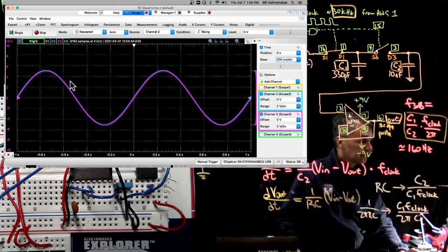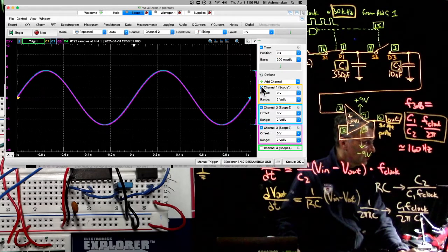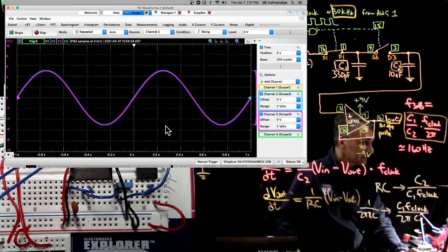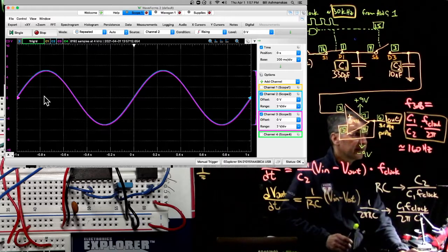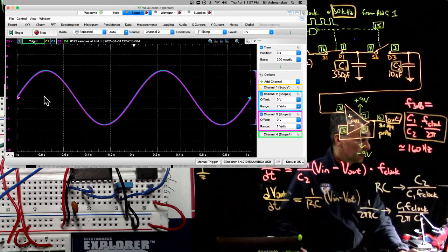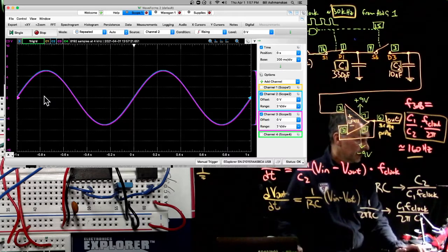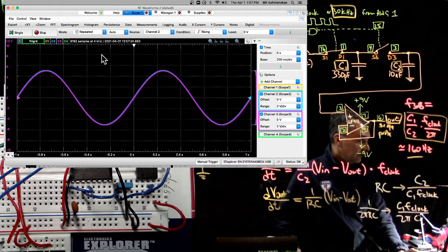Then let's look at the scope. Here's channel 1, which is looking at the 30 kilohertz clock. That's kind of hard to focus, so we'll look at that later. Channel 2 is the blue or cyan trace. That's what we're sending in. Channel 3 is the magenta or violet trace. That is what we're getting out. Right now they seem to overlap perfectly. This is at 1 hertz, and I predict that F3dB is about 160 hertz. So let's go up to 10 hertz.